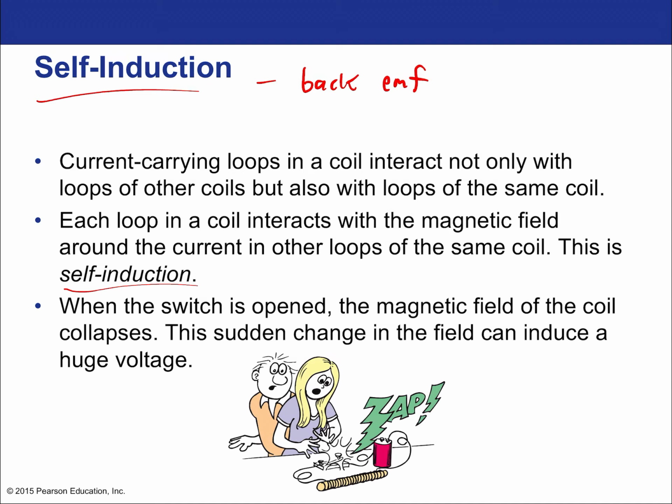But the point is that when you're running that motor, and that motor is turning, it's creating a changing magnetic field that is inducing a current. That current actually opposes the current that turned the motor in the first place. So the very act of the motor running creates an induced current that runs backwards from the current that ran the motor. Because remember, the only reason the motor is running in the first place is because of the force acting on the charges, right?